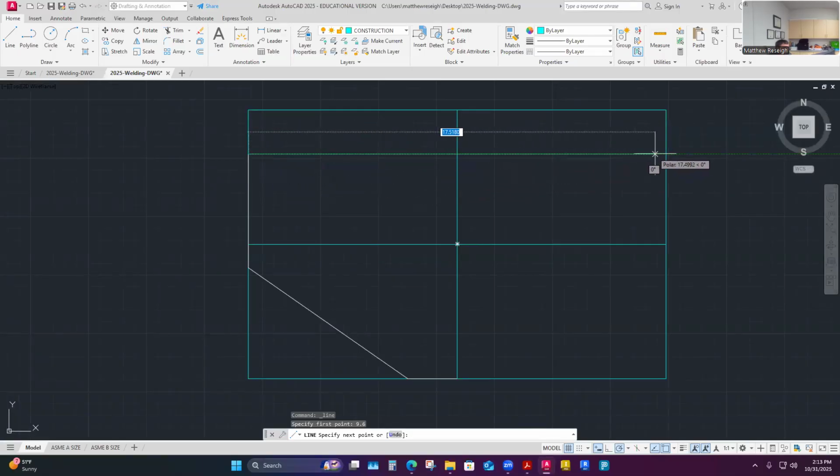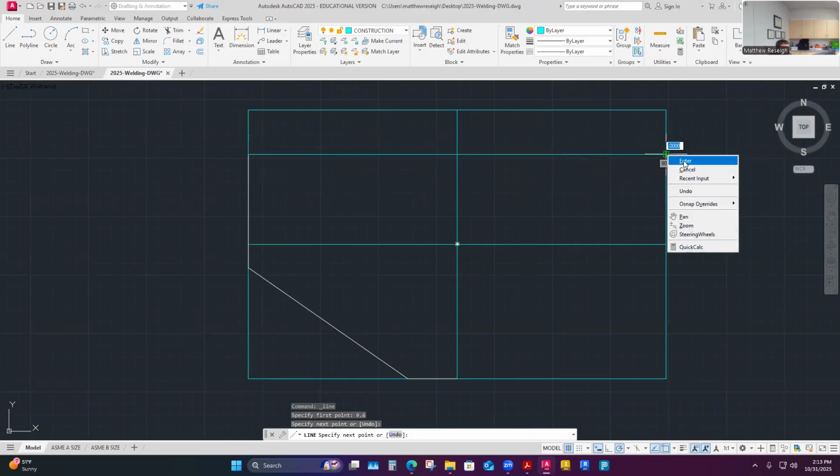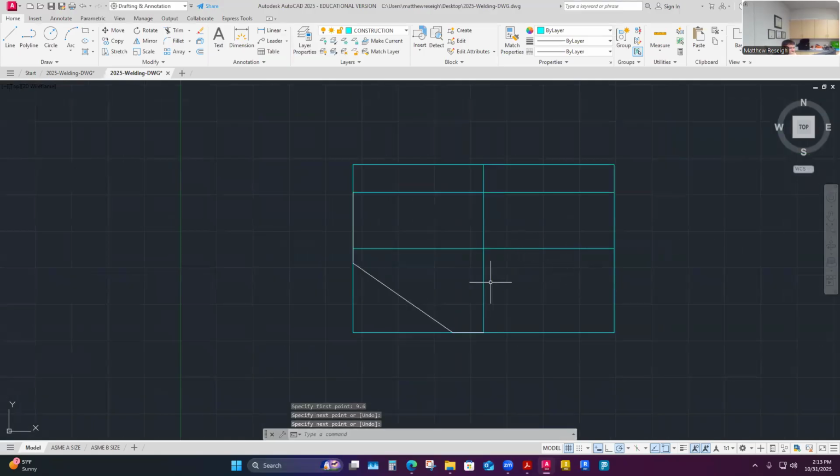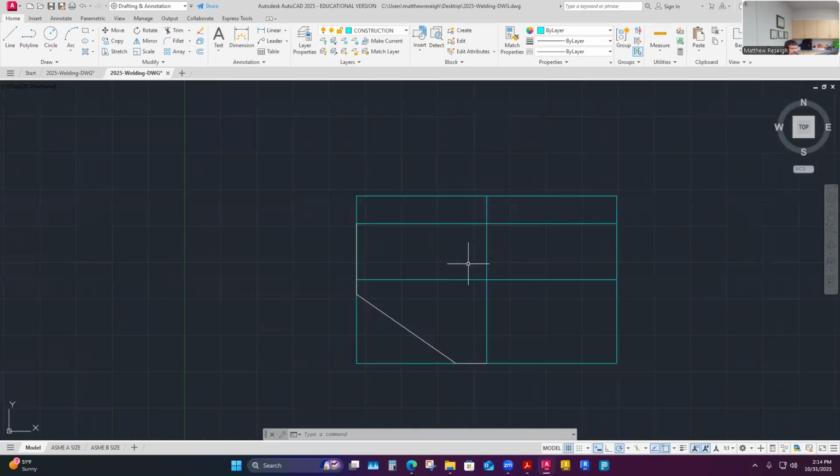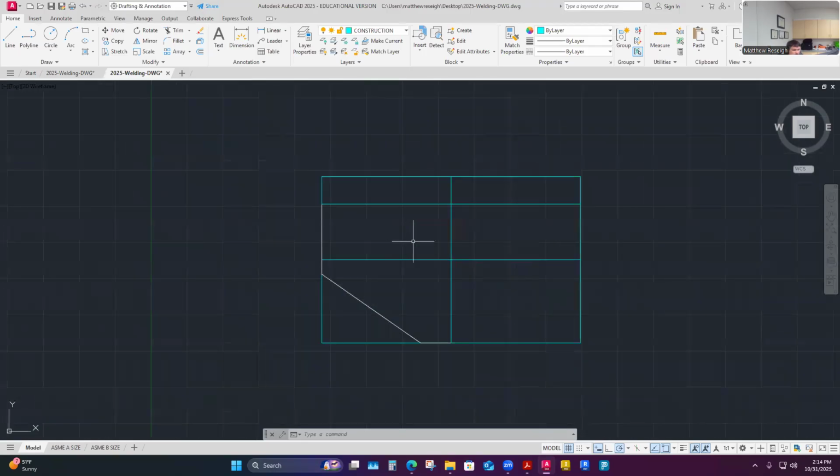It's a little bit like projection line work for mechanical drawing. I just kind of project this over. We're only building one view of this. And if you remember from your orthographic projection days, a lot of times we have to build multi-views of our geometry. That's why I would be ready to start projecting geometry over to the right side anyway, across this center line here. So I am carrying the projection through my view, and I'm even staging myself to potentially draw over to the next view. So projection applies in this just like it did in your mechanical drawing.